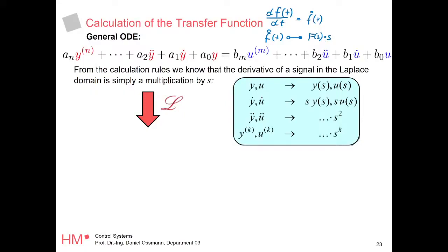We don't need to do a derivative. We simply bring it to the Laplace domain and multiply by s. So this guy here, if you transfer that back into the time domain, is immediately f dot of t, right? So you could actually compute the derivative without actually doing the derivation, by just doing the transformation twice. I hope you can see this workaround here. And the same goes for the integration, right? But here, for this calculation of the transfer function, we only need this certain rule.